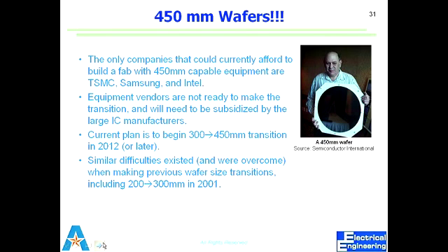Think about it, even a chuck which we use to hold a wafer, you cannot use a 2 inch wafer chuck with a 4 inch wafer, because that will have too much vibration once you rotate it at 4,000 RPM, for example. Does that actually create process difficulties? Like, does your spin coating still work with the same chemicals when you've got that much area? Okay, so that's now the chemical side, right? I'm talking about simple mechanics of this, that the equipment has to be completely changed when you do this shift from one size to the next.